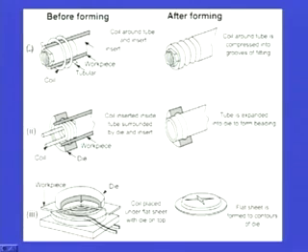So, how the diagram has been labeled: this is the coil that we were talking about, this coil is tubular, and this is the workpiece, the solid portion. Then there is an insert in between. This is before forming, and after forming we are going to get this shape. So, there is a tube and an insert, and a coil around the tube and insert, and here the coil around the tube is compressed into the grooves of the fitting.